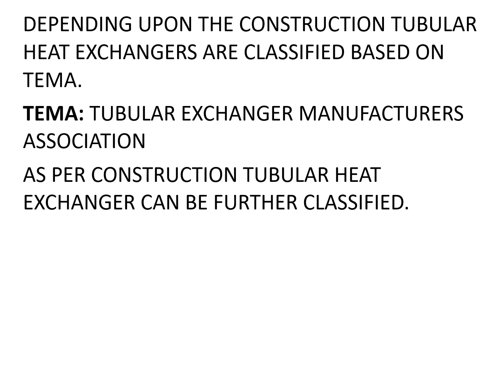They have decided to define what a heat exchanger is, how to size it, and what the overall coefficient has to be depending upon the medium. So all these things they have defined. What has to be the pitch between the tubes. So all these things are defined in the TEMA standards.